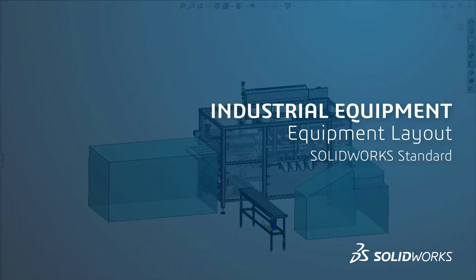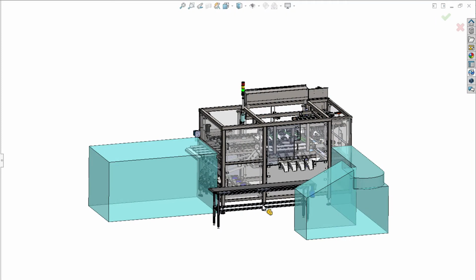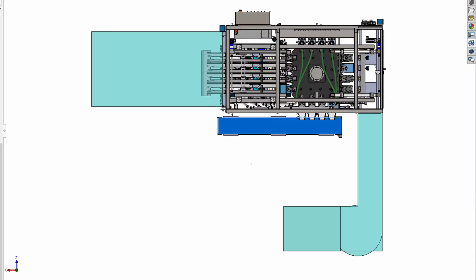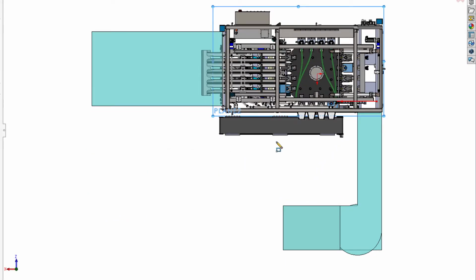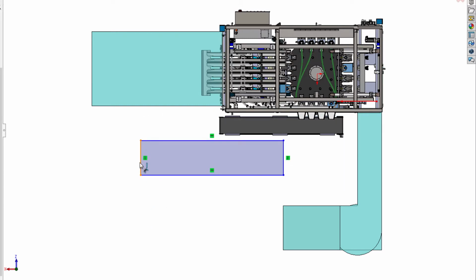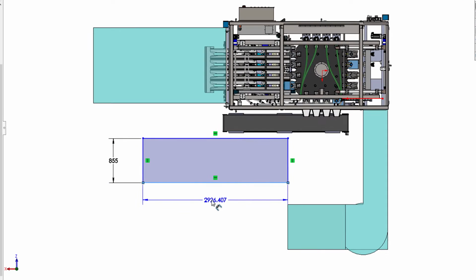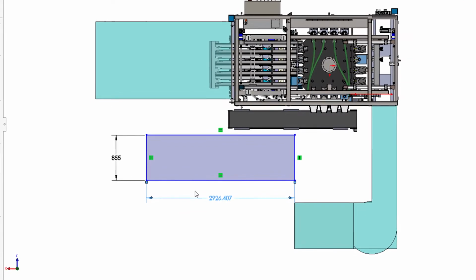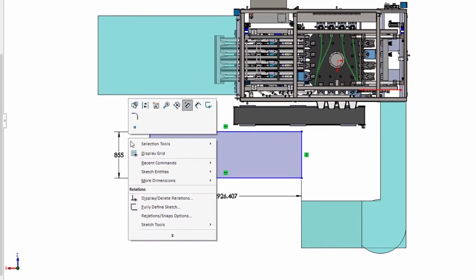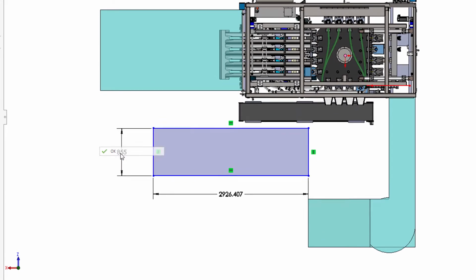Using magnetic mates, this conveyor automatically snaps to the ground plane, making it easy to position. The second conveyor needs to accommodate 4 soap bags, so this design definitely needs to be tweaked. In the meantime, I can use an assembly level sketch to rough out a placeholder for it and get an idea of exactly how big it really needs to be.